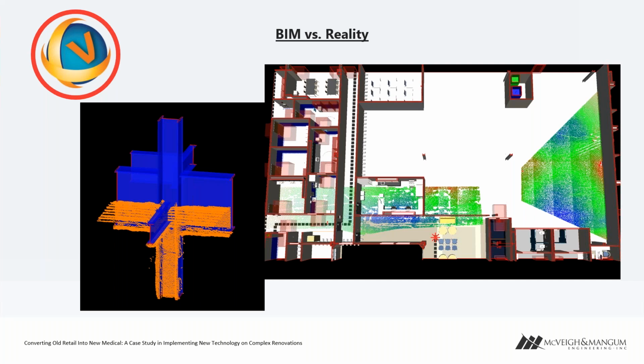But when we were in design, we captured the as-built and compared that to the design models that were being built off of as-built drawings. So now we have a degree of how far we're off. We found beams that were shown sloped on the drawing, but when they were out in the field, they weren't. Those are things we were able to pick up, and we were also able to understand the exact height we had within plenum spaces, and understand where we were going.